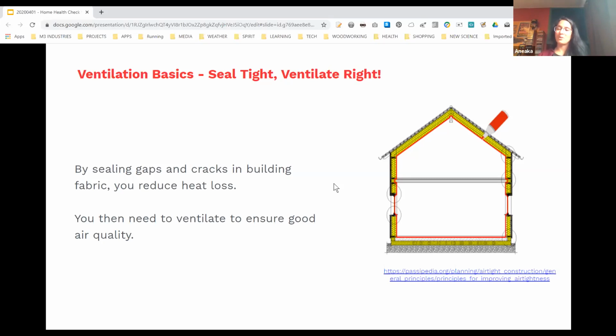You can imagine the air doesn't flow so well because it's coming in through all the different gaps. Then if you imagine a completely new box, totally sealed, with one inlet for air and one extractor fan, you can imagine what the airflow will look like. That's a really good illustration that your ventilation system will work better and more efficiently if your home is more airtight.